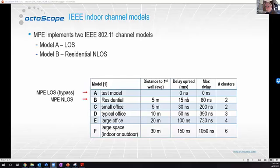Now we're focusing on the residential model because that's very representative of a lot of consumer deployments. Actually, our multipath emulator emulates 2 of the IEEE models defined in that paper. The first is Model A, which, as we mentioned, is a direct line of sight, flat frequency response, no delays, no spectral nulls.